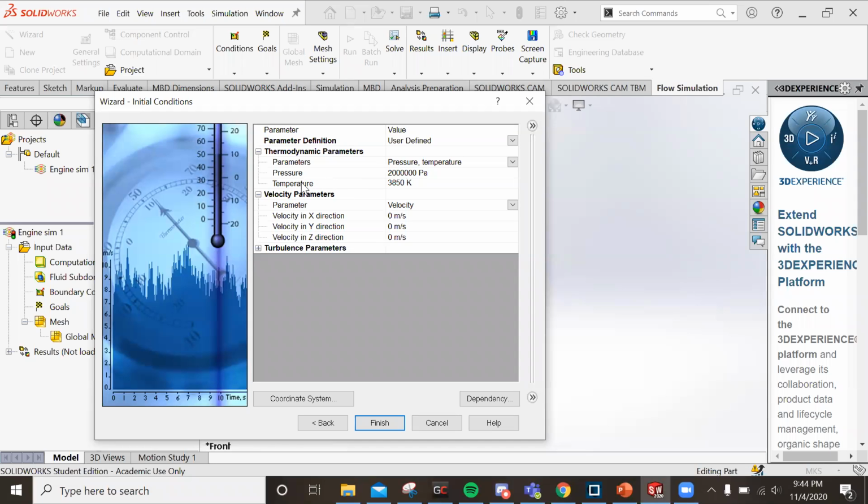It is actually pretty important that you set the temperature to be around your combustion temperature at least. Fluid properties change with temperature by a very much non-negligible amount, especially when you're talking about something on the order of 3,000, almost 4,000 Kelvin. So that is going to affect things. But also, like I said, you don't need to change this yet. You can leave it as the defaults and change it later, but I just did it to illustrate now.